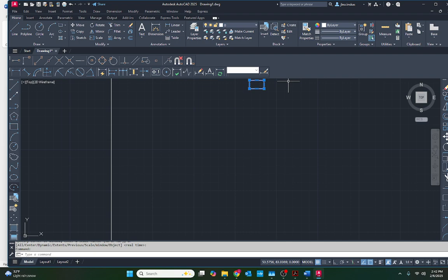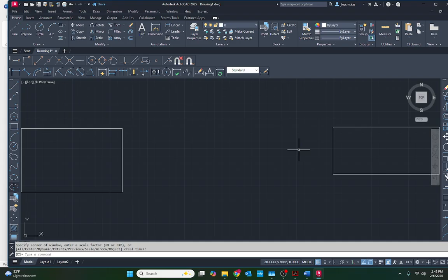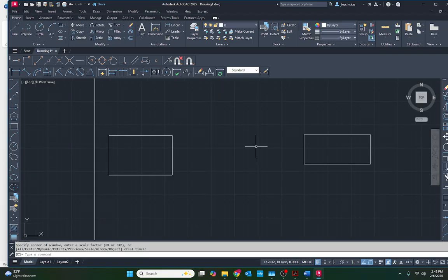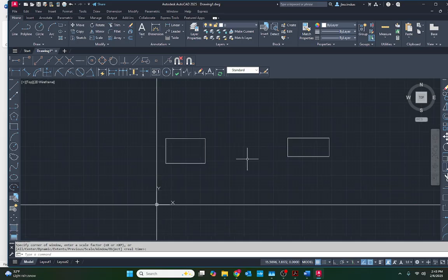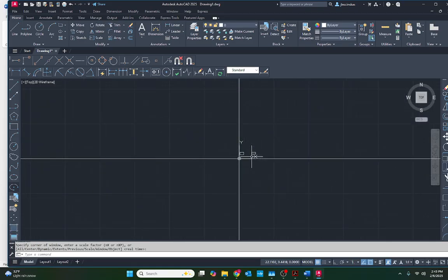So typically what you would do is your zoom extents, and then roll back the scroll wheel by 1 or 2 clicks to get a view that works for what you're doing. You should always make sure you're using a view that allows you to see what you're doing. So you shouldn't be, let's say, trying to connect these 2 boxes with a line in some kind of view that looks like that. It's really not appropriate. Okay, so with that said, we've gone over pan and zoom.